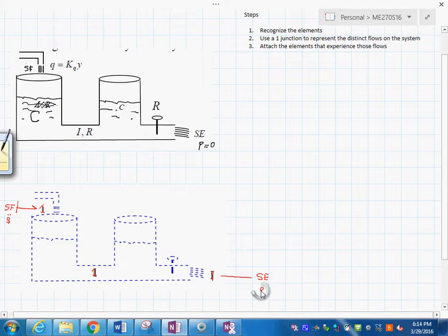And we need to put a little arrow in here, which is for an activated bond, which in fact says that the flow is free flow in there, but this is not putting any pressure onto the system, but rather is the reference pressure, in this case the atmospheric pressure.